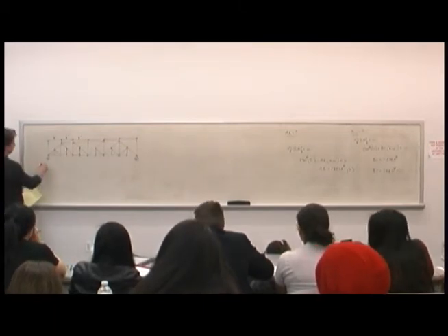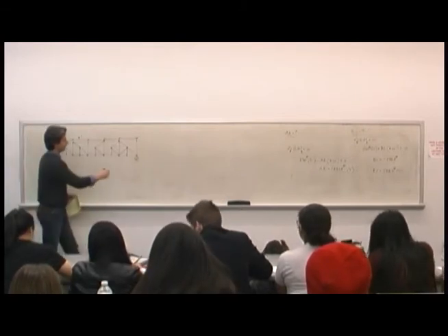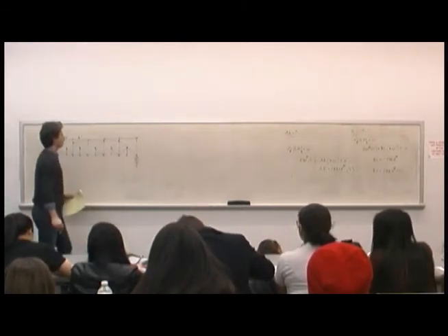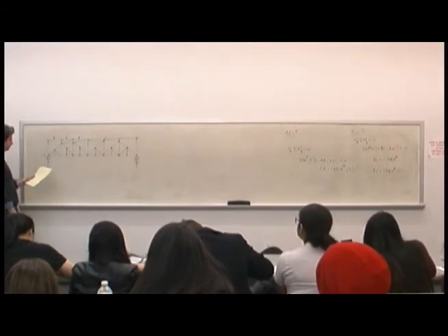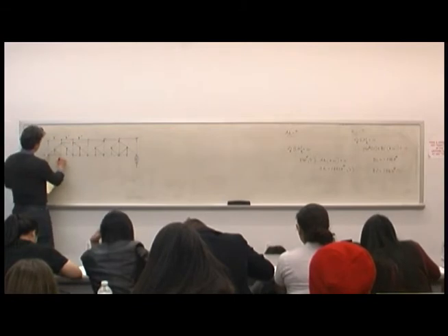So if I have this structure, I have a pin over here, which means I have a reaction in both directions. Here I just have a vertical reaction. There are 4-foot modules, and I have different loadings.